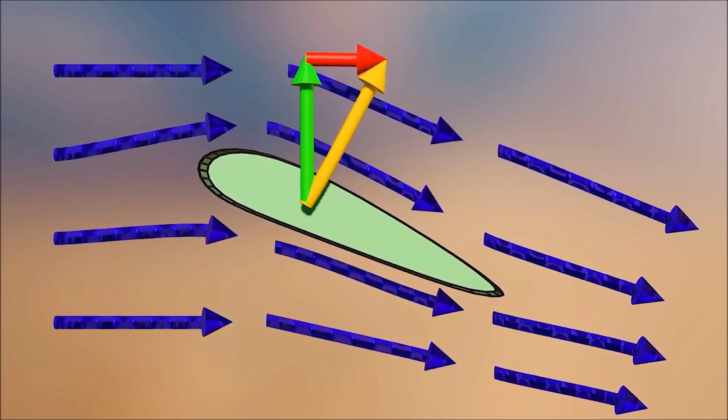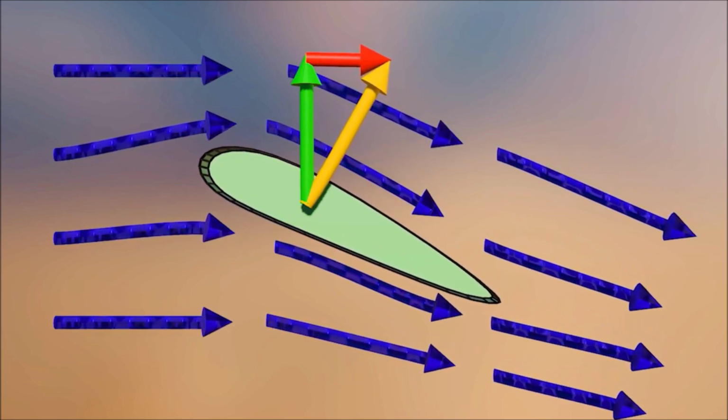More downwash means more air being deflected, resulting in more or the same lift even though we are at a lower speed. But as far as induced drag is concerned, what really matters is that the increased deflection of the airflow at lower speeds means the lift is inclined further back, resulting in more induced drag.